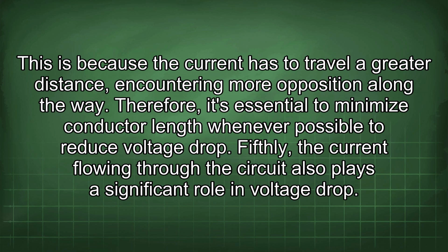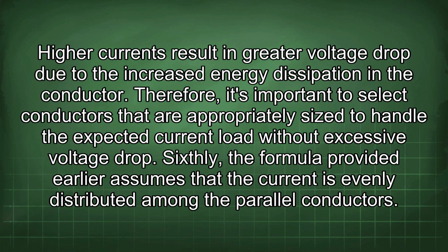Fifthly, the current flowing through the circuit also plays a significant role in voltage drop. High currents result in greater voltage drop due to the increased energy dissipation in the conductor. Therefore, it's important to select conductors that are appropriately sized to handle the expected current load without excessive voltage drop.